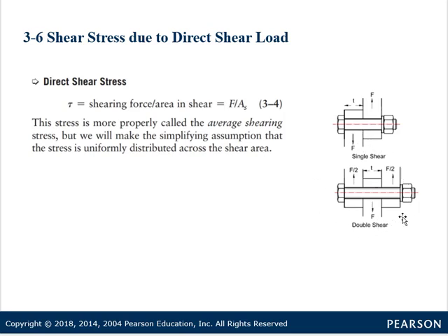Now, in this lower case, we have essentially the same load, that's F, but we're carrying the shear load over two shear planes, and this is a condition we call double shear. Okay, so I want you to be aware of this when you're doing your homework. There's a couple problems where we talk about shear in pins.